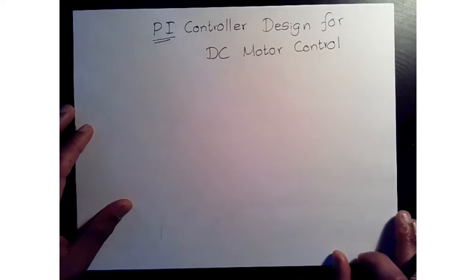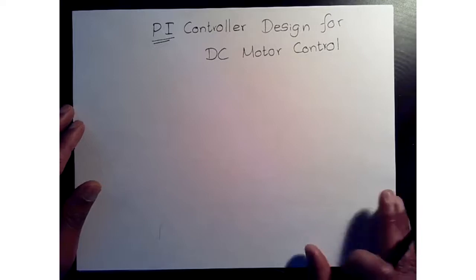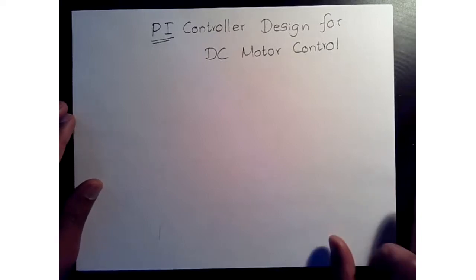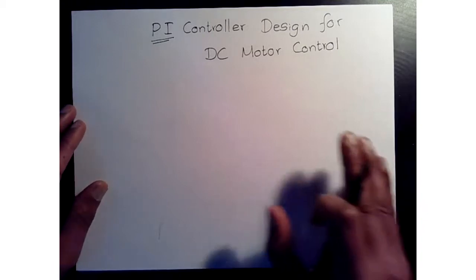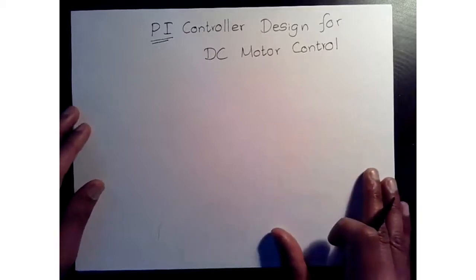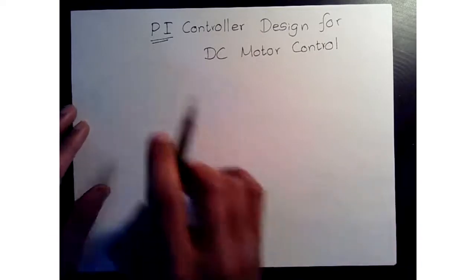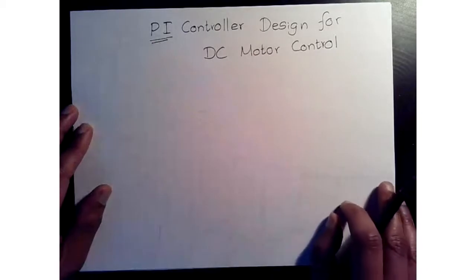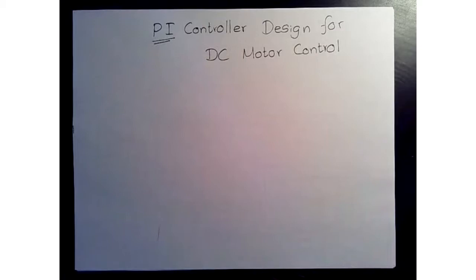Of course, you might want to do a servo control loop too, and if you do want to implement a servo control, then we'll have to look at the precision signal as well. But primarily, this discussion will be on developing either a current loop or a speed loop or a cascaded configuration. Okay. Now, for current and speed, a PI controller will be sufficient in most cases in applications that you see very commonly.